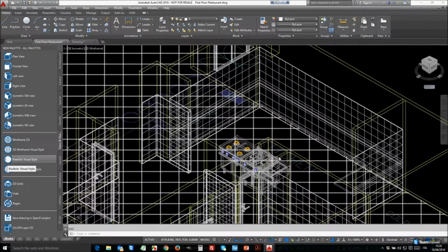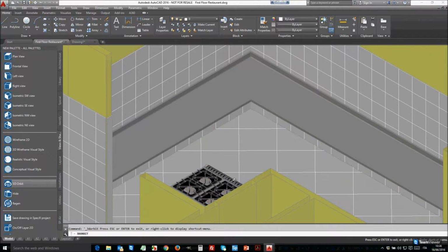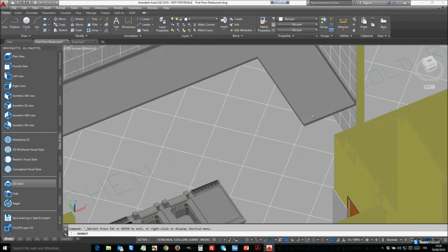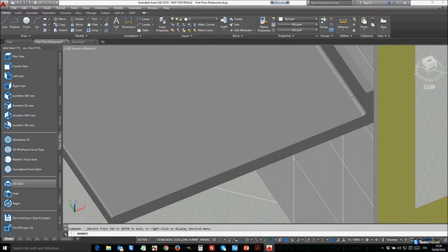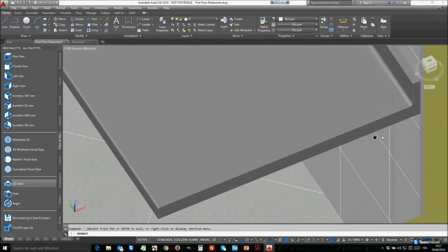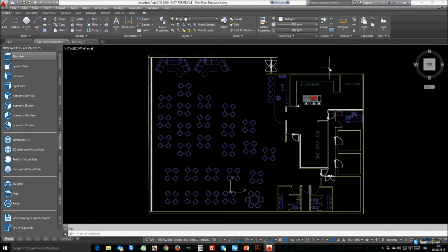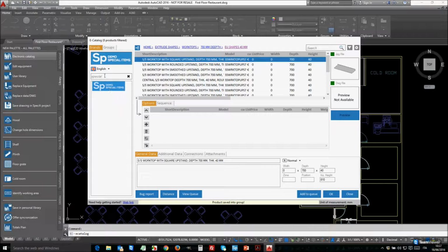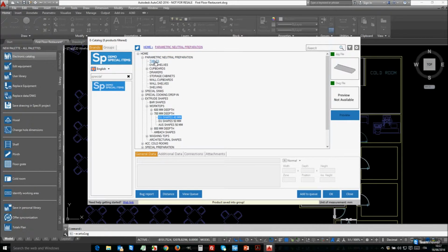You have to consider you have also ties at walls, so we need to use intersection and OSNAP. Okay, one time we finish, we can press enter button, and the software creates the profile and extrudes the profile in order to create the worktop. You can also rotate. So as you can see, it's very easy to work with the software because you work in bidimensional, but every object has been created in 3D, and you can see exactly the lateral shape that it extruded.